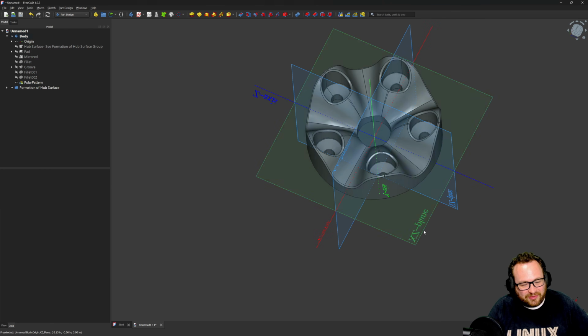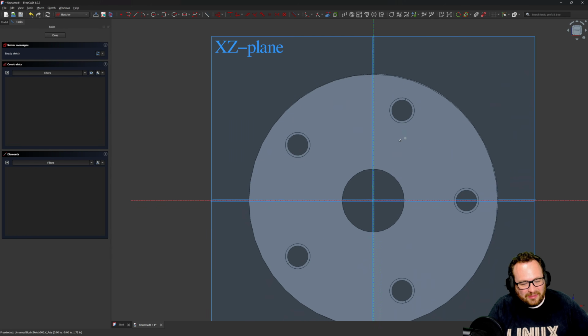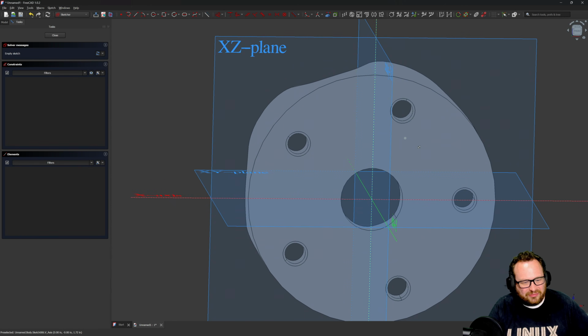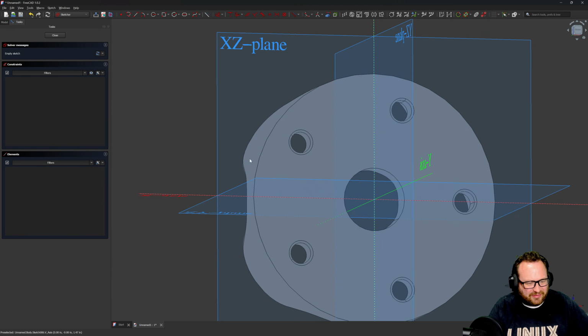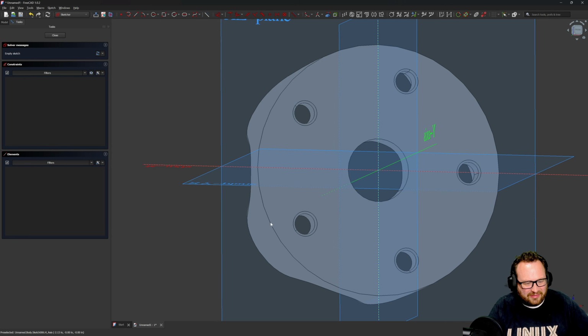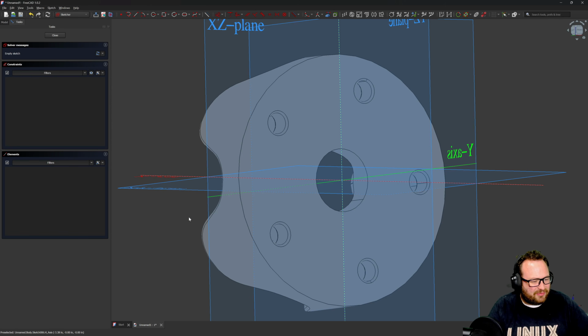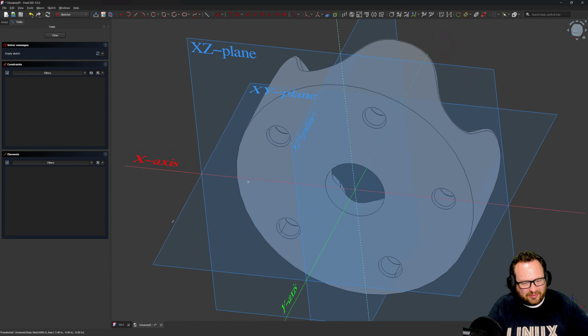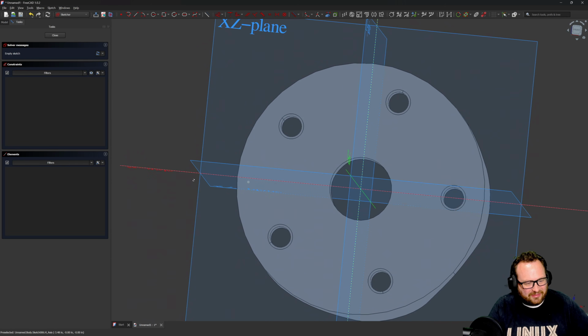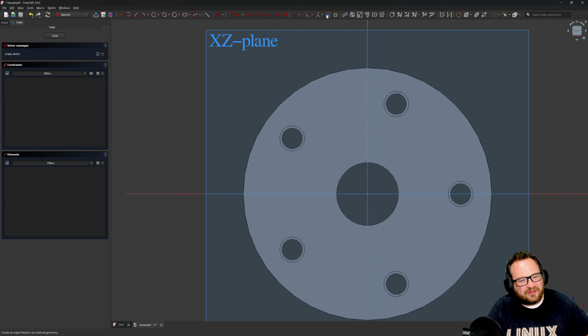So we'll choose our XY plane, create a sketch, and then make sure that I know where I'm oriented here. It looks like this side is what I want to work on. So reset my view, and I'm going to do this side where it's lowest, and this plane intersects the lowest point there. I think that's the only part of this wheel where you have that, and it is. I'm going to insert this geometry right there and there.